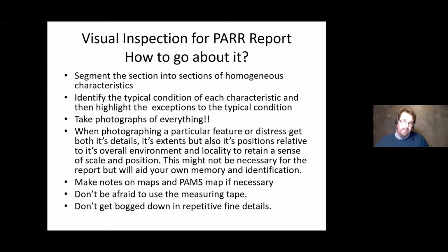And when you're photographing, just be conscious to photograph the element that you're looking at, so the particular crack you're looking at, but not just it. Try to get its scope, try to see how it's sitting in its overall environment and how it's approached by drivers, because this is good not just for your own records and for the PARR report, but also for your memory when you're writing this down back in the office.